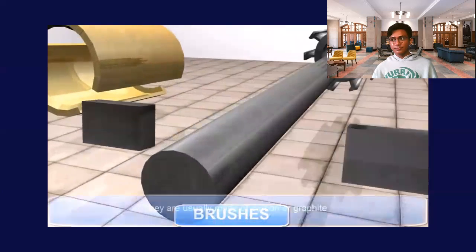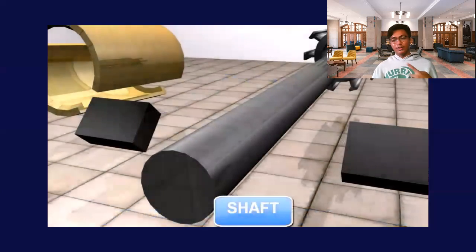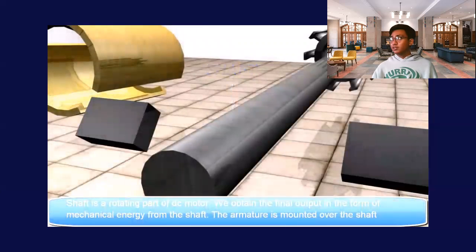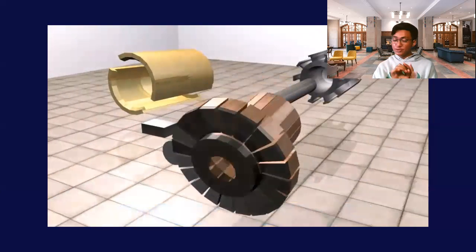Brushes. They are usually made of carbon or graphite. The main function of brushes is to collect current from the moving commutator. So the current will flow into the brushes, go into the commutator, and then go back into the brushes before going to the negative terminal. We obtain the final output in the form of mechanical energy from the shaft. The armature is mounted over the shaft, the rotating core, where we can put a gear on the shaft, we can put a fan on the shaft, and so on.